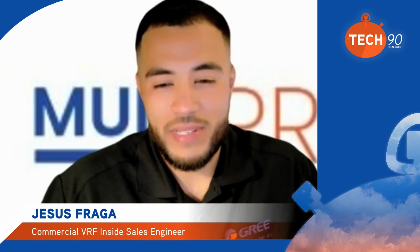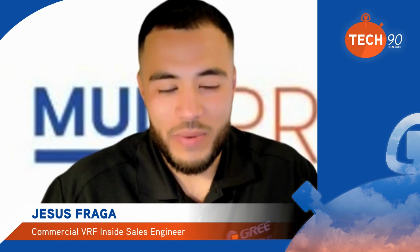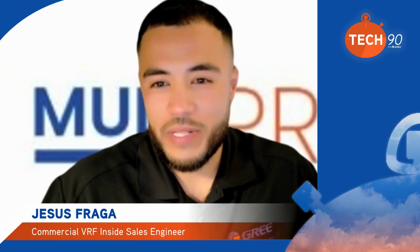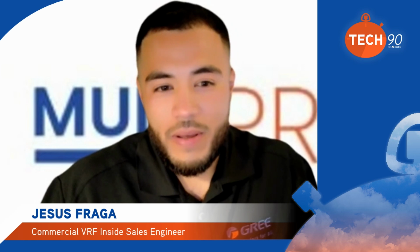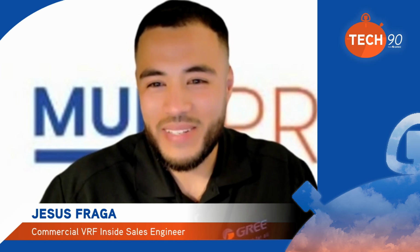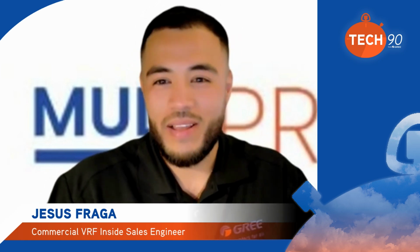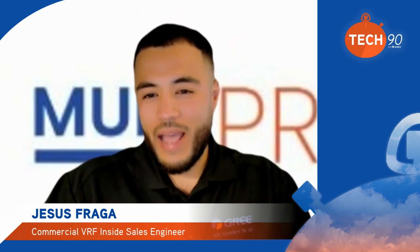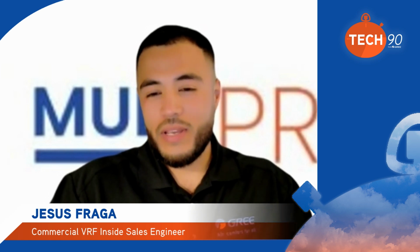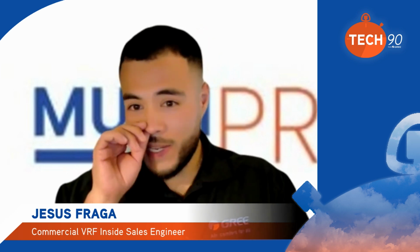So I did want to add on top of that, Greg, another thing to consider, one thing that I've seen a lot back when I was in the field is the positioning of the registers. There were so many times I would go to a house for another issue, but they were like, this thing really cools really well. And then you come to find out there's literally a register pointed directly at the thermostat. So what is that going to tell you? It's going to cool off. As quick as the air comes on, it's going to already satisfy the temperature. It's going to start shutting down. And in inverter-driven systems, they have that time delay for when they actually do turn off, so it's just going to take a little bit for it to react. And so Jesus, if you had that scenario, what was your fix?